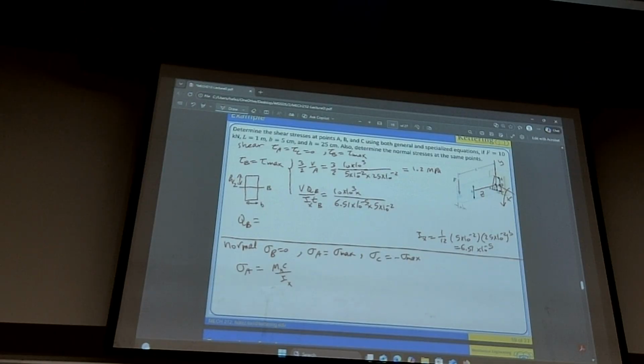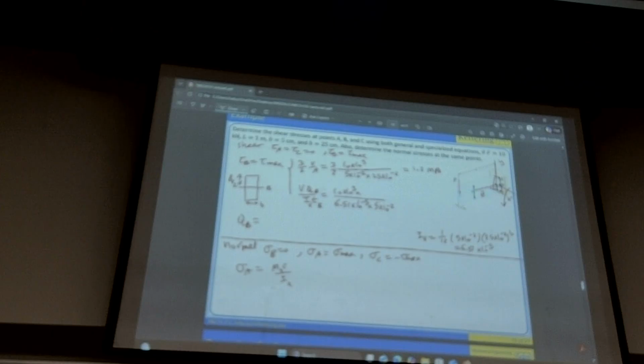So please, can I have your attention? This is important. If you do not pay attention to this, the text may not be explained this clearly. I'm interested in calculating Q for point B. Look at the cross section. Go either top part or bottom part, it doesn't matter. Pick one, stay with that. This is symmetric in this case, it gives you no preference. Well, let's go with the top one.